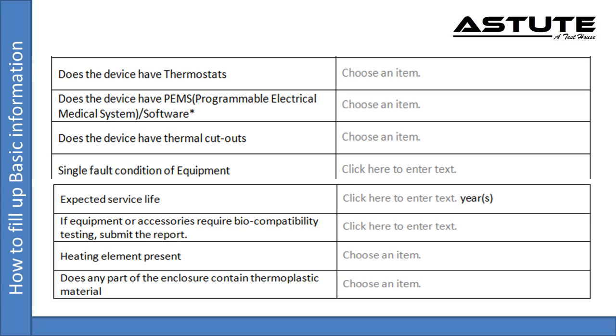ME equipment, its parts and components that heat a flammable anesthetic mixture with oxygen or nitrous oxide shall be provided with a non-self resetting thermal cutout, as an additional protection against overheating.